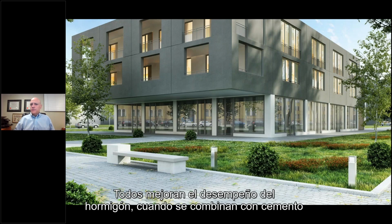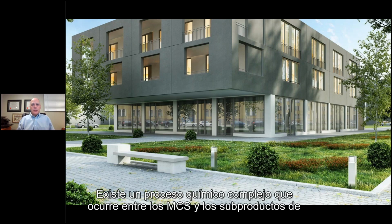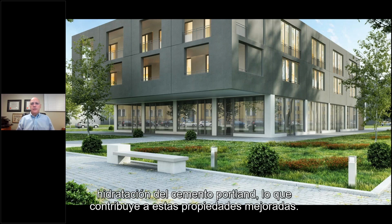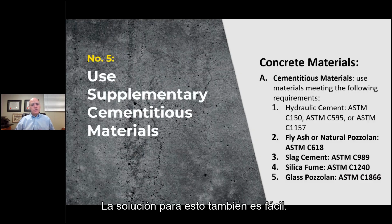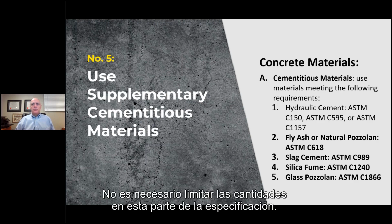All enhance the performance of concrete when combined with Portland cement, including increased strength, increased durability, and enhanced workability. There's a complex chemical process that occurs between the SCMs and the Portland cement hydration byproducts, which contributes to these enhanced properties. The solution for this one is also easy. Just list all types of cements and SCMs permitted by code and standards. There's no need to limit quantities in this part of the specification.